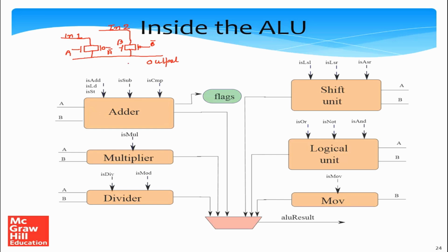So now if you would recall our discussion from chapter 6, let's say that A is 1. See, if A is 1, this transistor, the NMOS transistor, is on, and A bar is 0, so the PMOS transistor is on. So essentially this input is connected to the output. So the output will take up whatever voltage is there in this input.